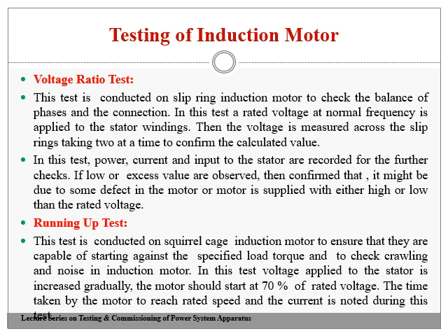But it becomes simple in a slip ring induction motor, since we bring out 3 terminals or 4 terminals depending upon the type of rotor connection, whether it is star connected or delta connected. If it is delta connected, we will have only 3 slip rings. If it is star connected, we will have 4 slip rings. Therefore, this test is conducted on only a slip ring induction motor.